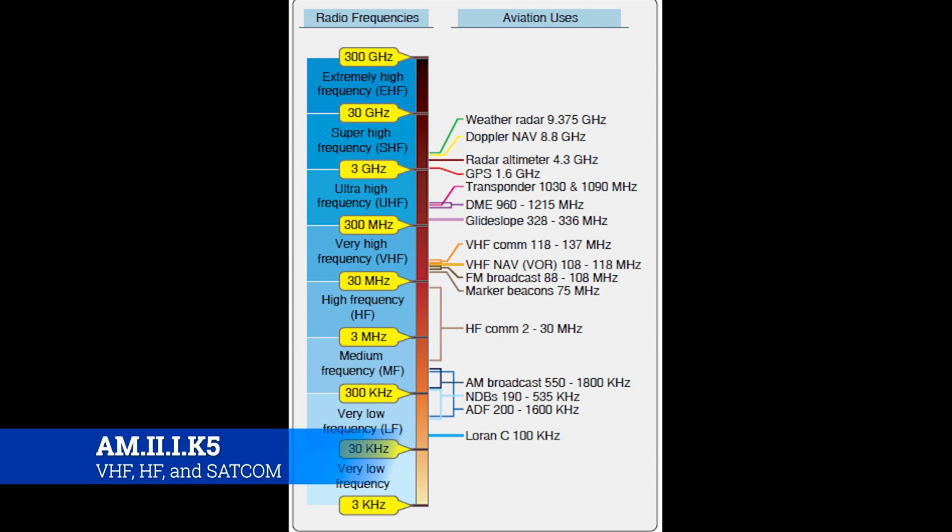So ADF is an automatic direction finder. You'll see those still, even in 737s. The MMR, the multimode receiver, can receive a lot of different radio spectrums or frequencies, and so they still have the ADF capability, though you don't really see it getting used a whole lot, but it can be, and you'll see ADF pop up on the screen if it ever does.